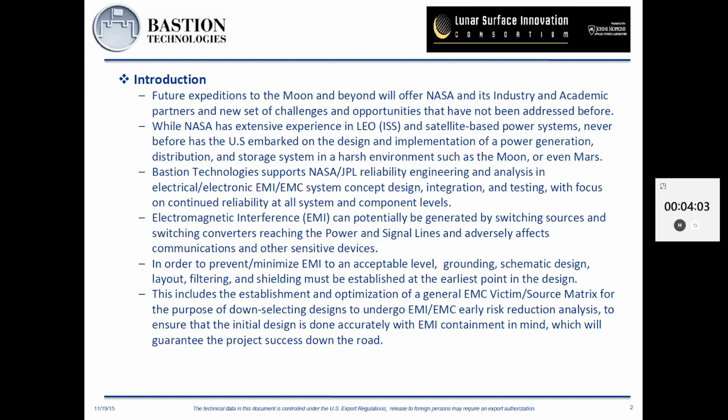Electromagnetic interference can potentially be generated by switching sources like DC-DC converters, and that can reach the power and signal lines and adversely affect communication and other sensitive devices. In order to prevent and minimize EMI to an acceptable level, grounding, schematic design, layout, filtering, and shielding must be established at the earliest point of the design.